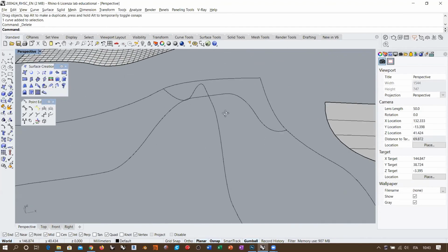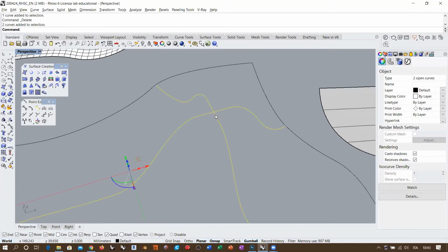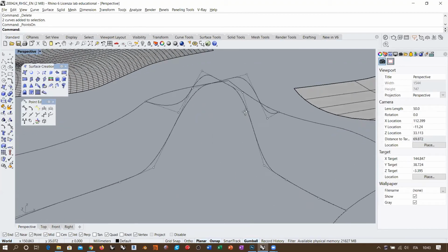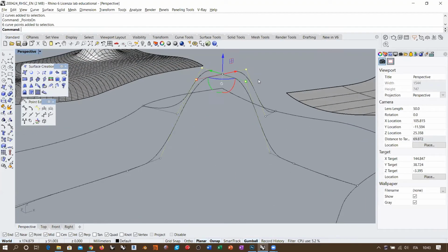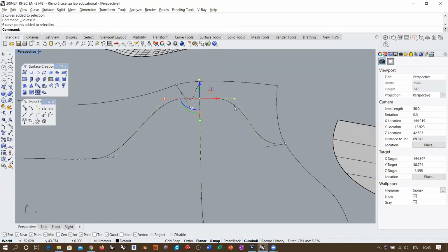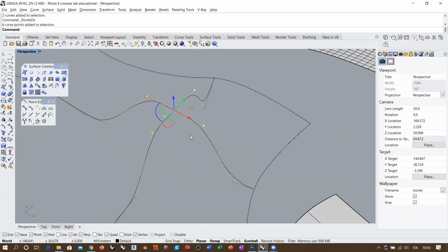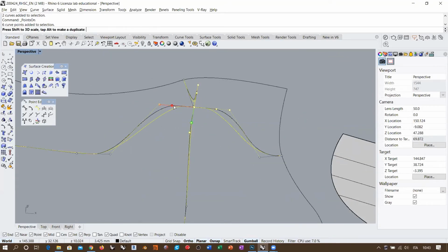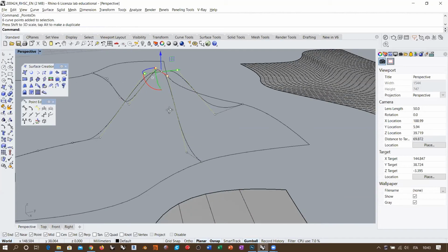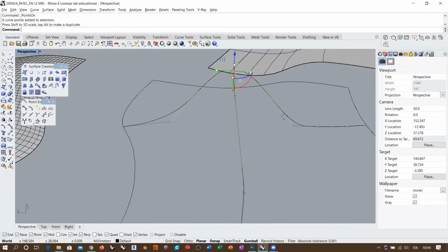And as we have access to the topology, we can activate the control points. We have this cross of points here, which we don't need the diagonal, let's say, because this is not a surface. It's not a two-dimensional domain. These are two unidimensional domains. Okay, so I only need 3 points and 3 points, and I can decide how rounded or how smooth or how squarish this bulge is.